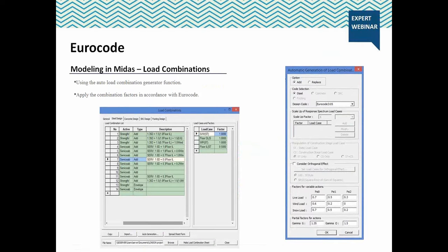Before we can analyse the structure, we wanted to create a few load combinations. We used the steel automated combination generator in accordance with the Eurocode, with safety factors of 1.35 for dead loads and 1.5 for live loads. As defined within the guidance of the Eurocode, these factors used in the checks on the structure allow for a design life of 50 years for a dwelling.